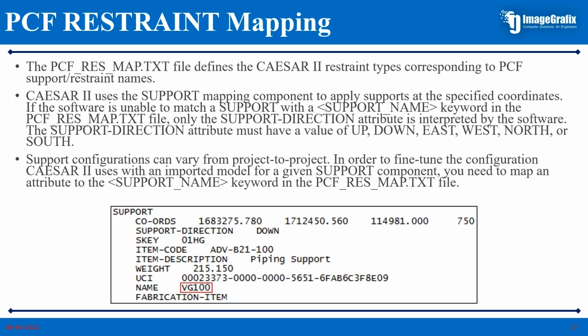But the application of those supports will be the primary thing for a stress engineer. I don't bother about what categories, how heavy the support is, or what shape the support is. What is that going to provide me in CAESAR? What does this support do to my pipe at that node number? That is what a stress engineer is concerned with.